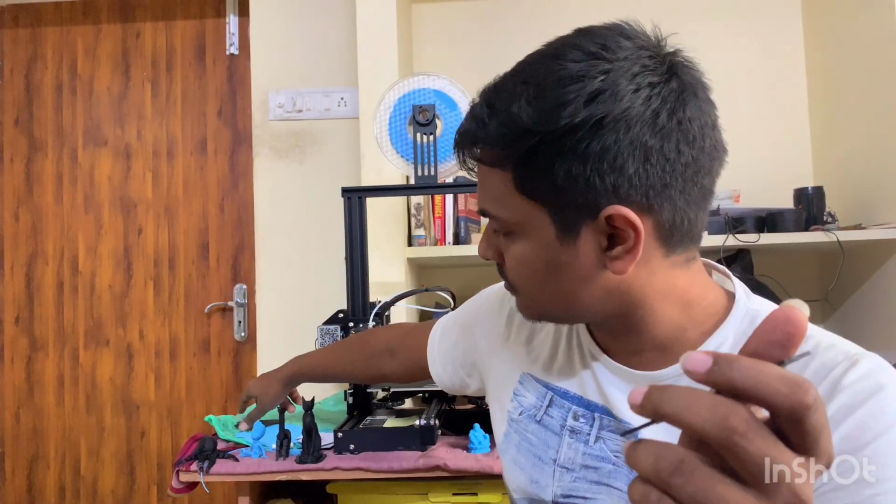I also have some failed prints from before, from which I came to know that there was not enough contact layer to be in contact with the printing bed. So in simple words, the more the contact layer, the better the printing material gets stuck onto the printing bed. Also make sure that while you're printing, you maintain the printing bed temperature at about 60 to 70 degrees C, so that the plastic has some sticky properties and gets stuck to the printing bed.